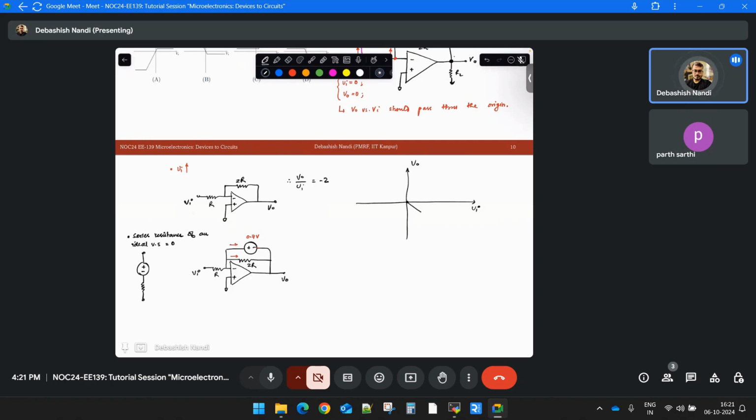So in this path you are seeing zero resistance and in this path you are seeing 2R resistance. So all the currents will be directed through this path. It will be as if this is not present or this is open circuited. So if this is your V out, what will be your V out then? This is grounded, right? From your virtual short configuration. So what is your V out?